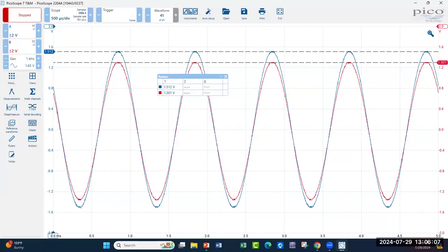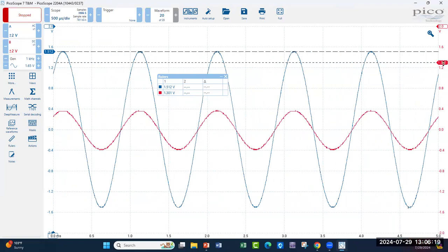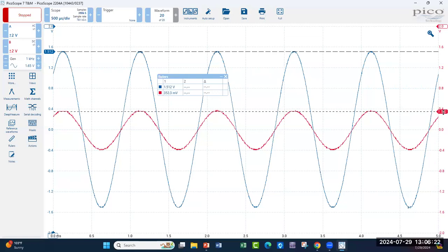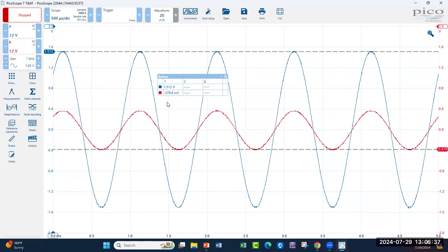And if I bring this back to point C, there's point C. Hit the run, stop, and bring my cursor back down. I can go to either. I've got a little flatness there. I'm going to go to this particular one. 379.4. So every once in a while, if you get on your trace, the way it draws this out, if you see a bit of a flat spot occur and you want to read the peaks as accurately as possible,